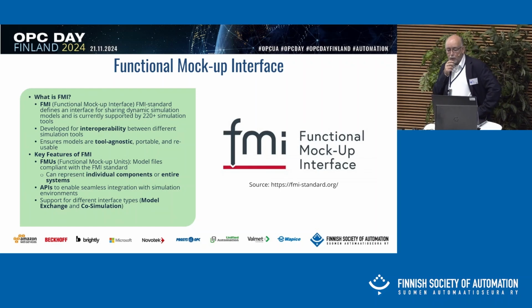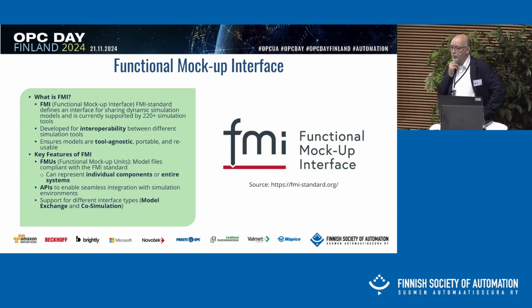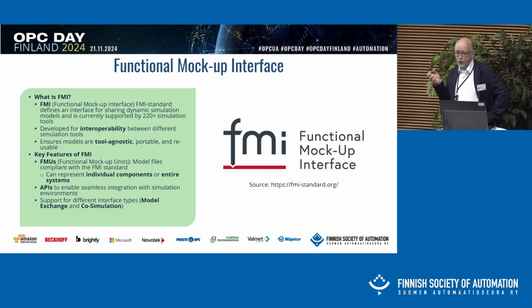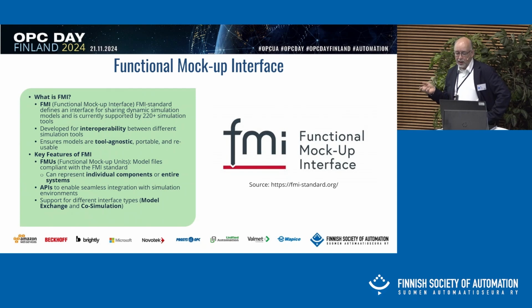So there are over 220 simulation tools, like MATLAB, Simulink, and you can compile and export the FMU file. The FMU file is actually a zip file that contains a description XML and the needed libraries to execute the simulation. So there is interoperability between the simulation tools, and that's also important. As with the OPC UA you can have different programming languages, with FMI you can have different tools to build these FMI models, and they are tool agnostic.